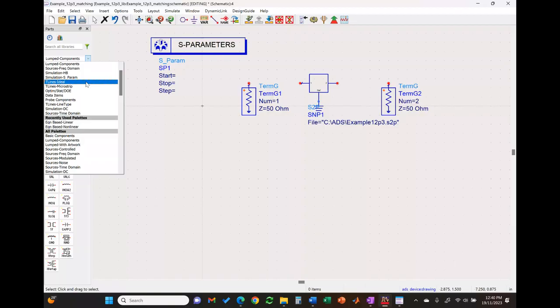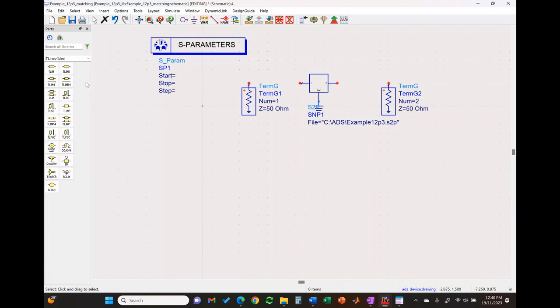For this purpose, let me delete this from here, delete this from here. You need to go and look for the transmission lines ideal toolbox, which you can see here in front of you. Then from this toolbox, the one that you need to use, at least in this course, is T-line, the first one. And how many do we have of these? We have 4.